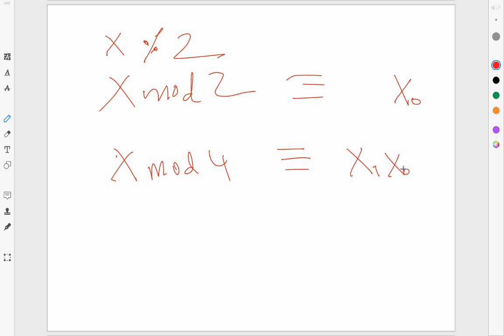The basic structure of making a bigger decoder is that I decode groups of bits and then combine the results. For example, I can take two 3 to 8 decoders. That will cover 6 bits. I have 1 bit remaining, but for 1 bit, all I need is an inverter to decode it into 1 to 2. Then I can combine the results using AND gates. So one solution would look like two 3 to 8 decoders and a single bit. But that may not be the lowest cost.